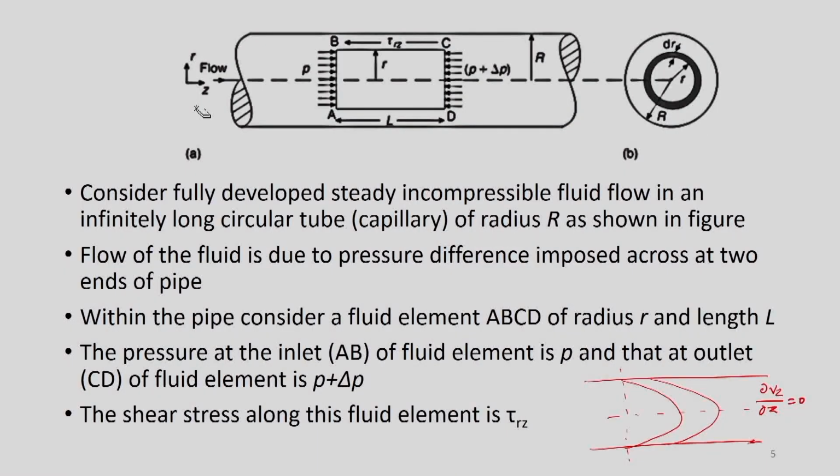There is no angular velocity, only the z component of velocity exists, changing only in the radial direction, and that is a true assumption as long as the diameter of the capillary is small enough, very small enough.